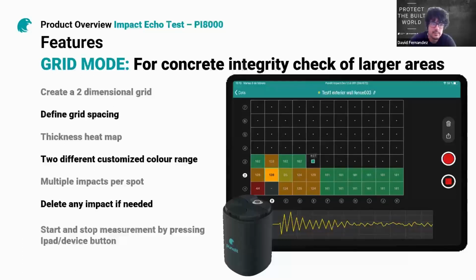Okay. And the grid mode is more interesting when you want to scan larger areas. So you can create a two-dimensional grid scan. You can always define the grid spacing. So you can define the horizontal dimensions and the vertical dimensions, which can be different. It doesn't have to be a square as it is in this example. And then once you have finalized it, you will have a thickness heat map. So in this particular example, you see that our concrete element has a thickness of around 180 millimeters. So it's very likely that this area has some kind of defect, as we are not getting the same signal.